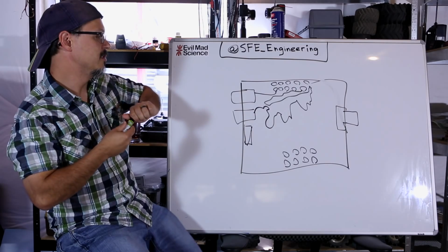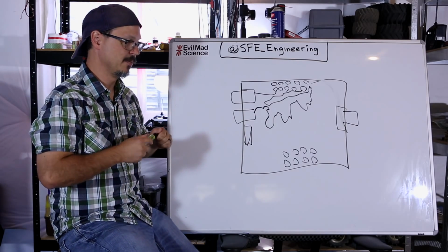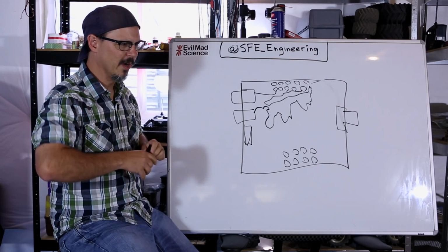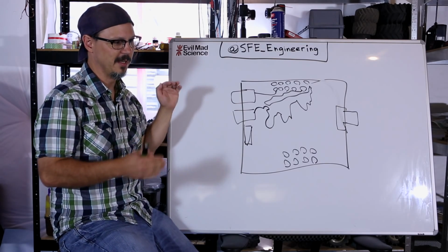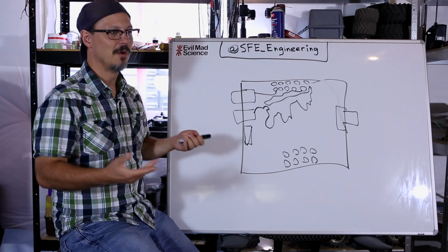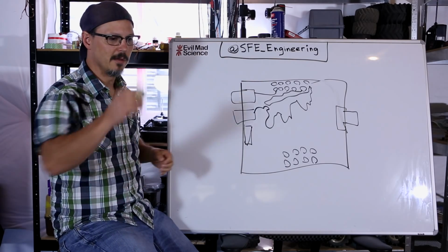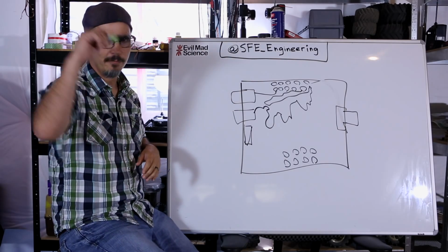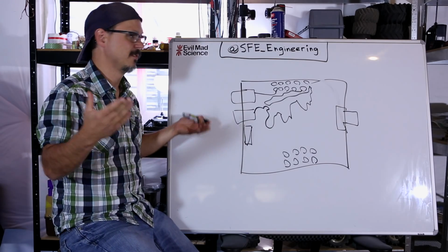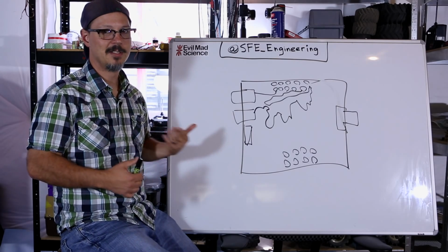Another thing that we do is we tend to avoid right angles in our traces, and the reason is because a right angle in a trace will actually round your edges. Like that. So if you're running logic, which everybody is these days, right? A trace with a lot of right angles in it is ultimately going to round an edge, and of course logical devices read edges, so you need that edge to be relatively intact.